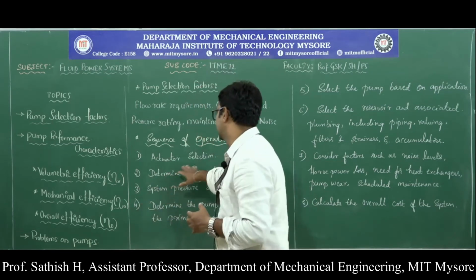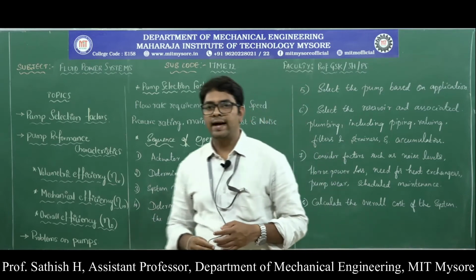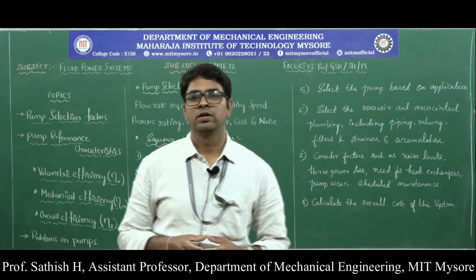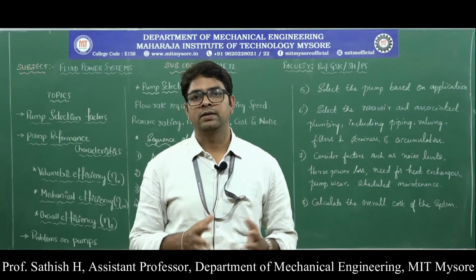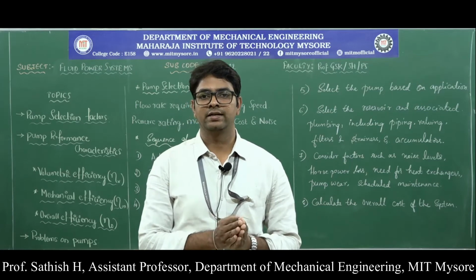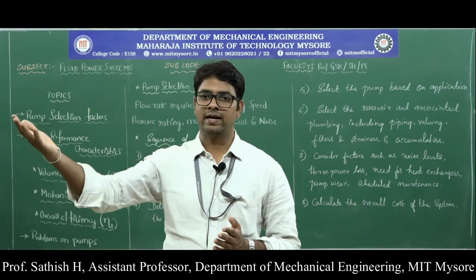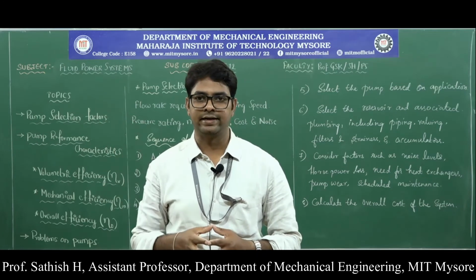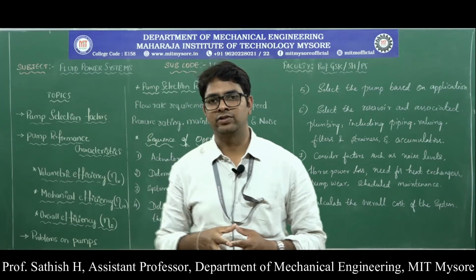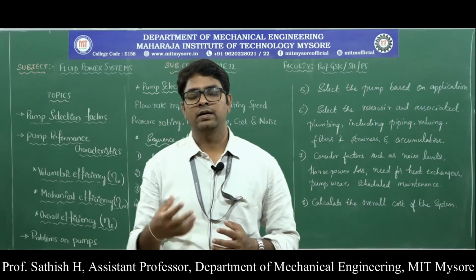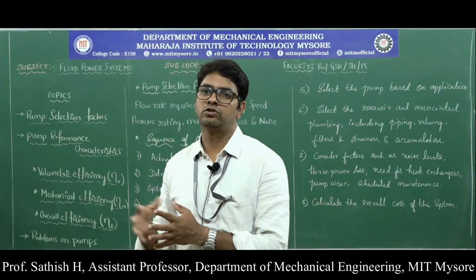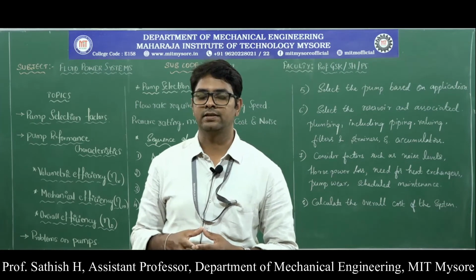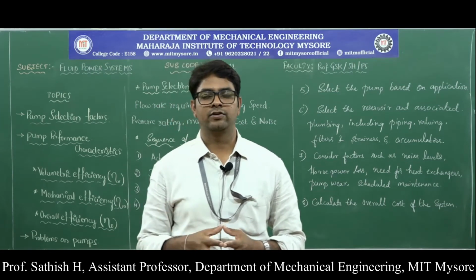The first one is the actuator selection. The actuator is where the work is done in a hydraulic system. At the actuator, the fluid energy, or pressure energy, or hydraulic energy is converted into mechanical energy, for example the lifting of a weight at the actuator end. Actuators are also called hydraulic cylinders, because they are a kind of piston and cylinder assembly, or they are called hydraulic motors.